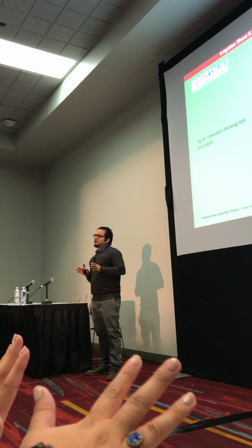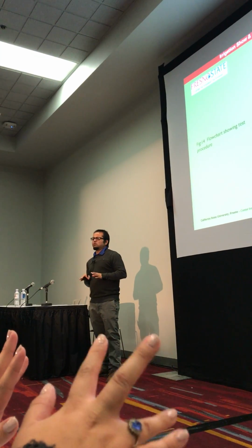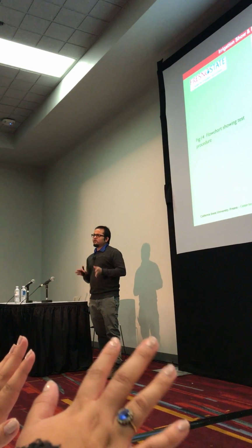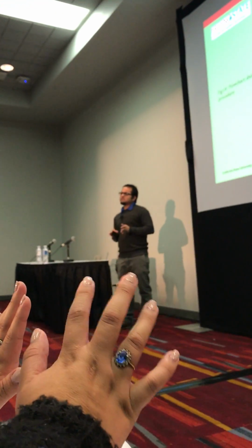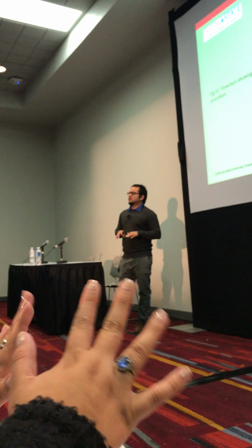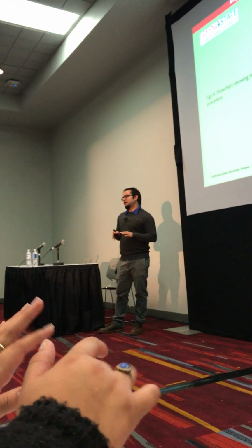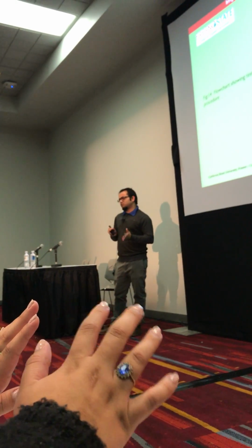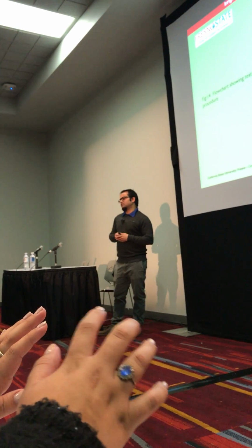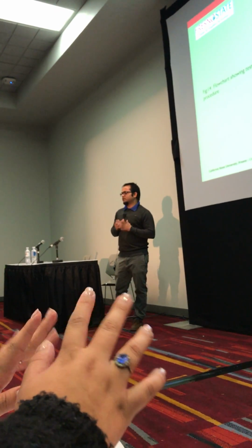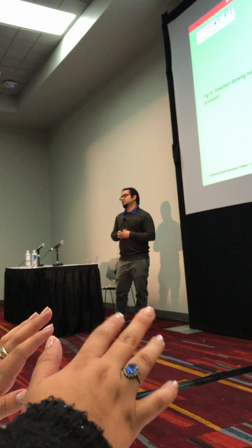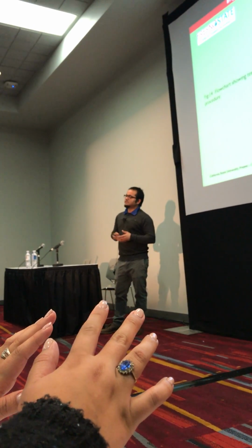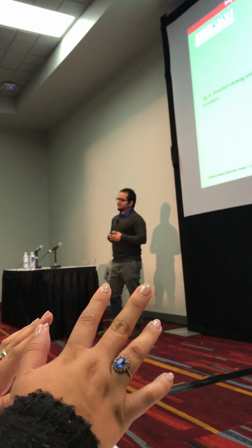We saturate the soil, normally watering for about an hour, and then leave it to dry. Once the water drains out, we leave it for about 24 hours, then measure the weight and calculate the volumetric water content at that point, and we call that field capacity. But we found some issues with calling it field capacity, so we also call it container capacity.